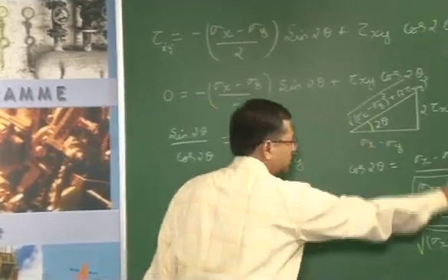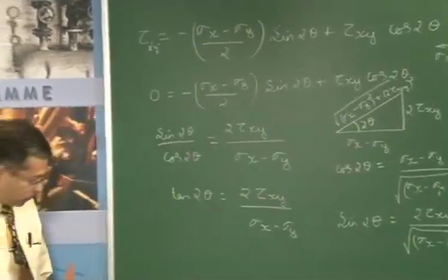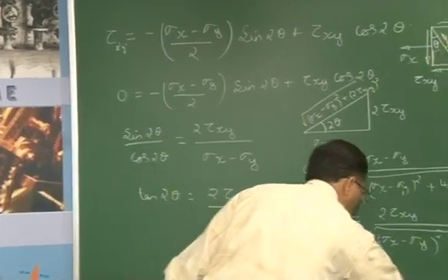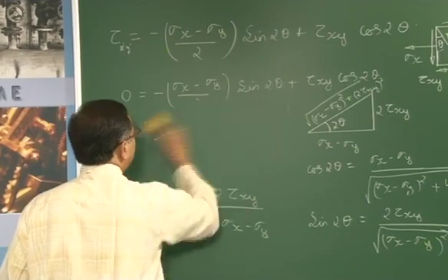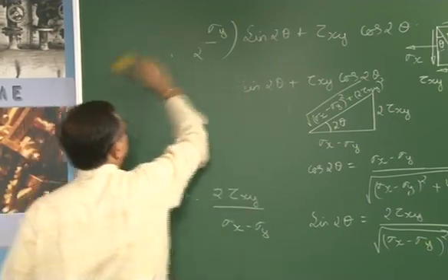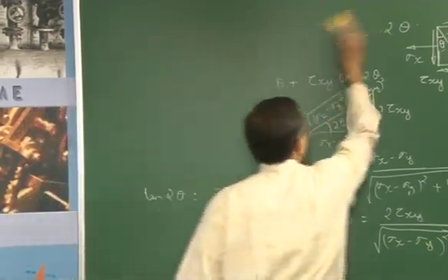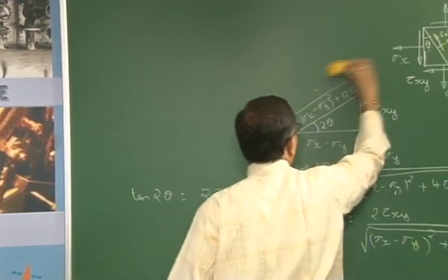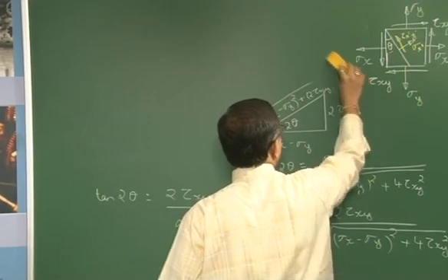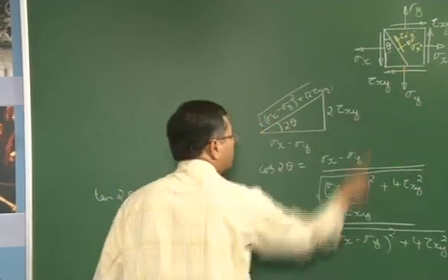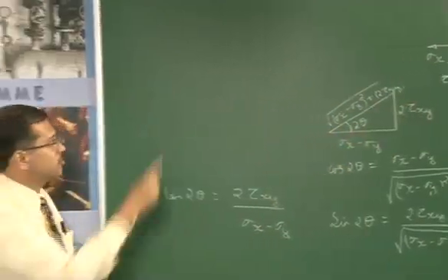So, I have got this now. To get the equation for the normal stress, which would be the maximum value, called the principal stress, let us take the expression for the normal stress acting on the inclined plane, which we had derived in the last class for a plane stress system, indicated in this diagram.